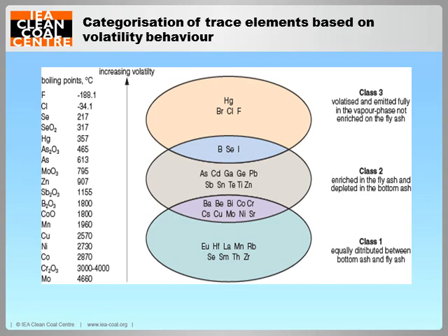Elements partially or fully vaporized undergo additional transformation and partitioning downstream as the flue gas cools down in the upper furnace and heat recovery section of the combustion system. The conversion of trace elements is determined by three complex and interrelated processes, including adsorption, condensation, and chemical transformation.